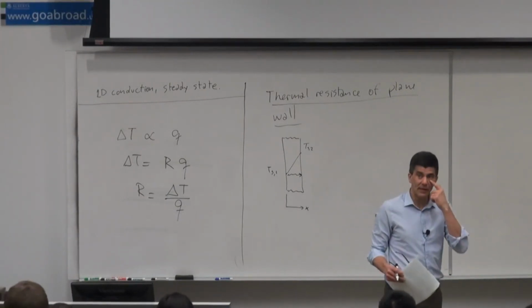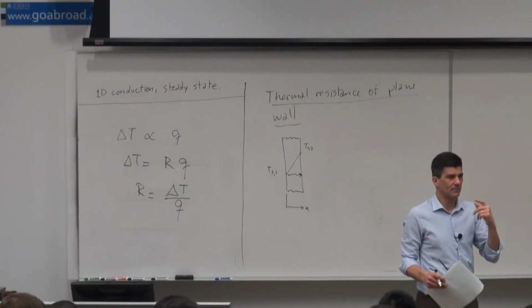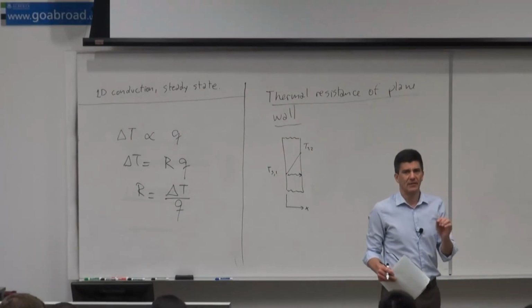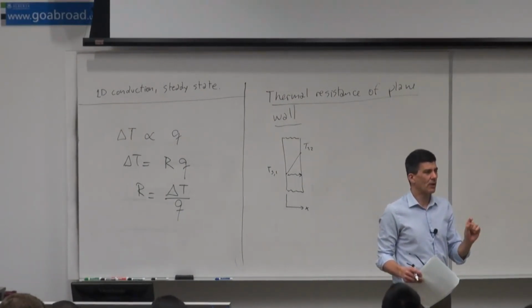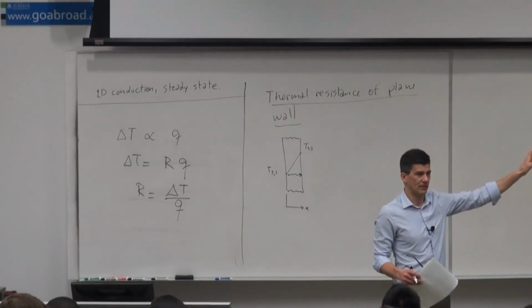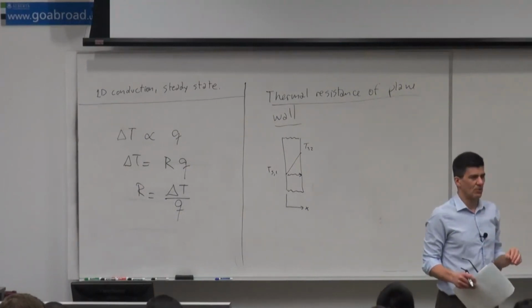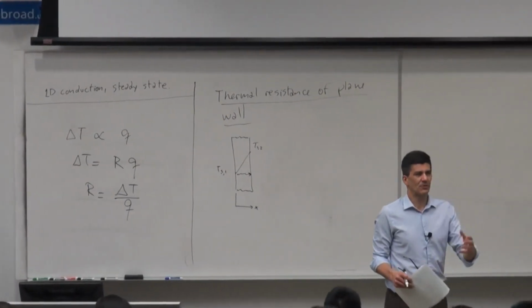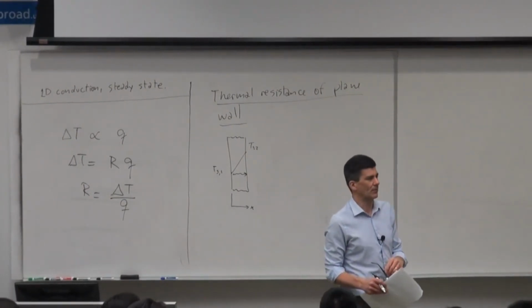But that's the radiation in the visible wavelength, which is just shy of a micron, and that corresponds to 6,000 Kelvin. That is the temperature of the surface of the sun. Now, we seldom work with those temperatures. We work with 20 degrees, 100 degrees, 1,000 degrees. But 6,000 Kelvin, very uncommon.